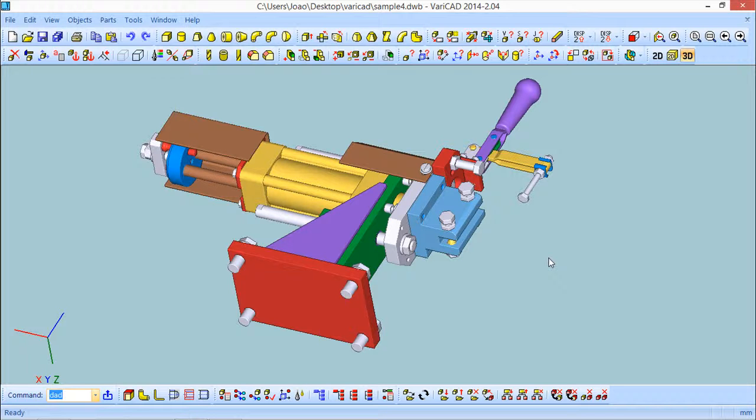It is very useful to have the similar parts of a machine or an assembly grouped, okay? And when we have them grouped, we can work very easily in terms of visibility, changing some characteristics of this group of solids, and even for the definition of sub-assemblies.